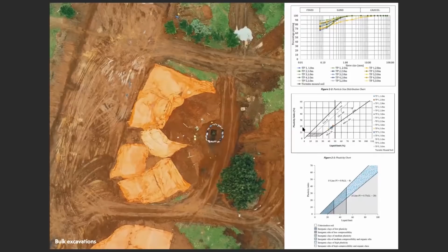What I'm almost forgetting to say is that this can be characterized by the particle size distribution. So the clay is the lower part of 0.002 millimeters, and then between that and 0.075 you have silt, and between that and about 6 millimeters, depending on the standards you follow, either 6 or 10, you have sand, and above the sand you have the gravel. And the composition of this soil will determine the strength that you can get, and will also determine whether you actually can compact this soil, or whether this soil is anyway suitable for construction.